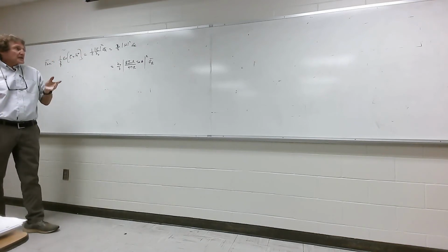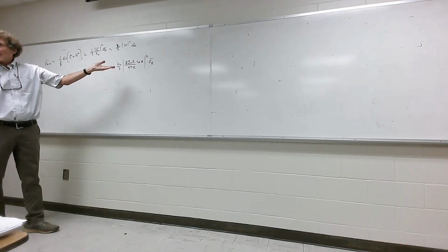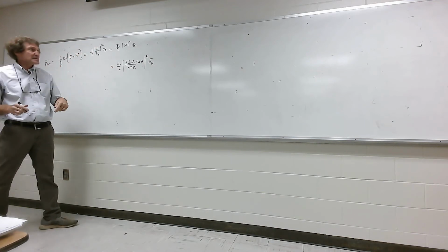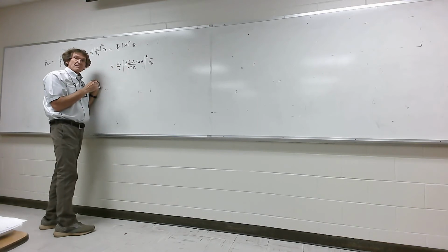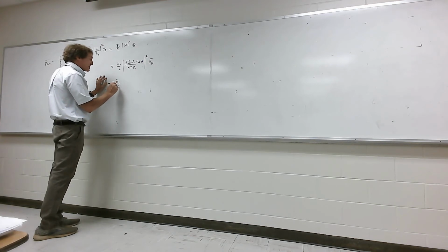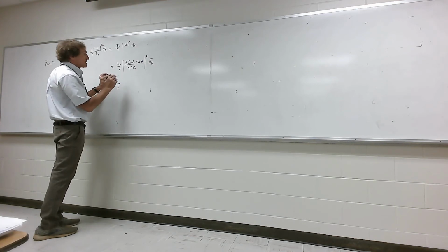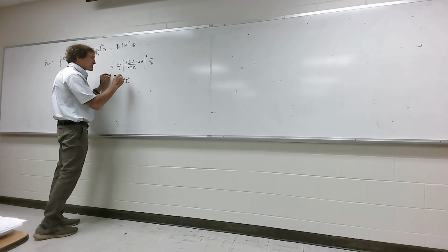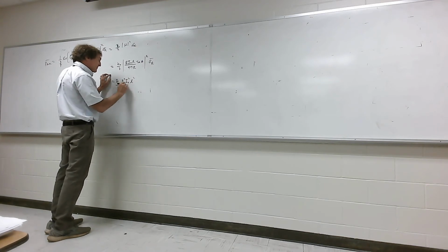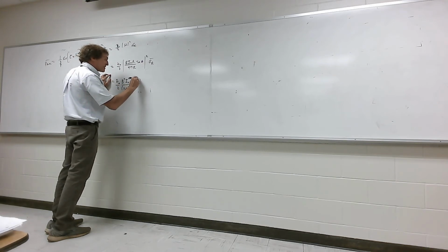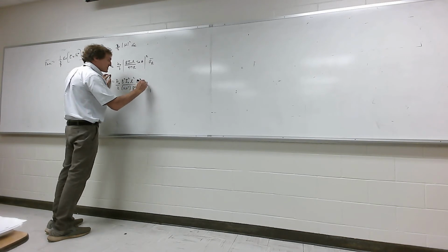Now the only thing I've done is I know what the H field is, you may not, but you just take the E field and get rid of eta naught and you got the H field. And I don't care about the phase stuff, I don't care about that j or e to the j beta, because it's going to be magnitude. Then you got to square it. So this comes down to eta naught over 2. Then I'm going to have beta squared, I naught squared, L squared, divided by 16 pi squared, r squared, and then it's sine squared theta. And that's in the a_r direction.